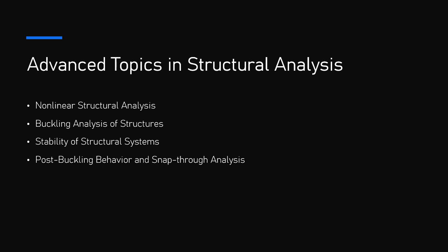The P-delta effect is typically analyzed using second-order analysis, where the additional moments and forces due to displacements are included in the load deformation response of the structure. Nonlinear analysis tools can be used to accurately model and account for the P-delta effects in tall buildings and other structures subjected to large lateral forces.